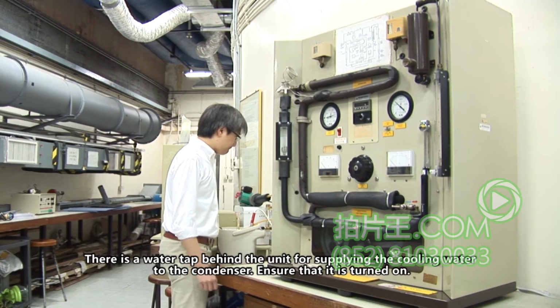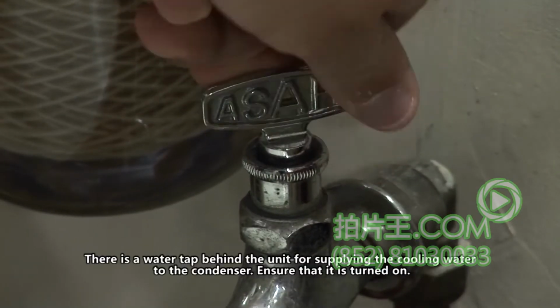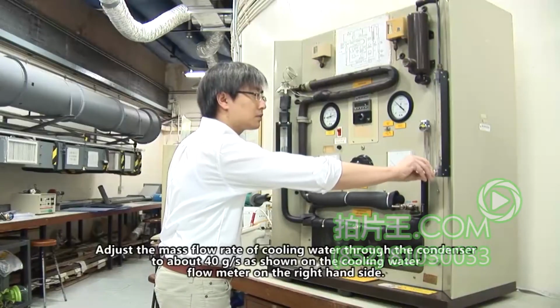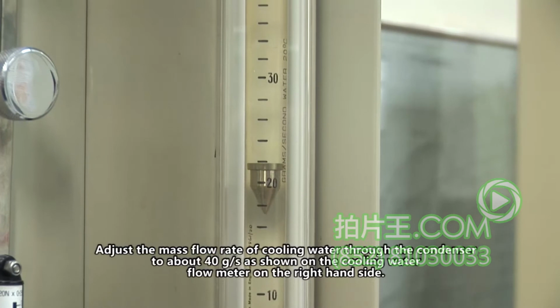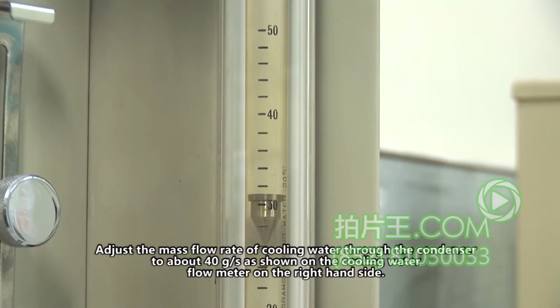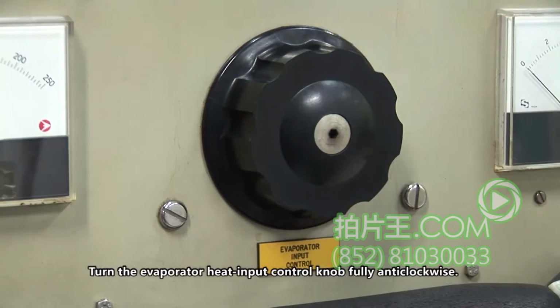There is a water tap behind the unit for supplying the cooling water to the condenser. Ensure that it is turned on. Adjust the mass flow rate of cooling water through the condenser to about 40 grams per second as shown on the cooling water flow meter on the right hand side. Turn the evaporator heat input control knob fully anti-clockwise.